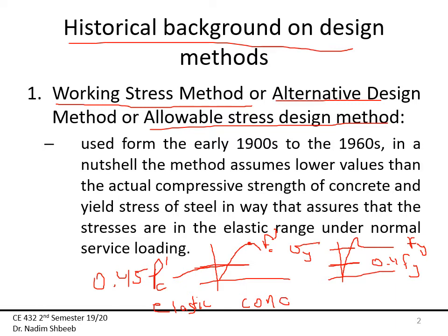As far as the loading goes, I'm not using any safety factors here. I'm just using whatever normal or service loading I have, because all the safety is applied to the strength properties of both the steel and the concrete. So that's what we call the working stress method.